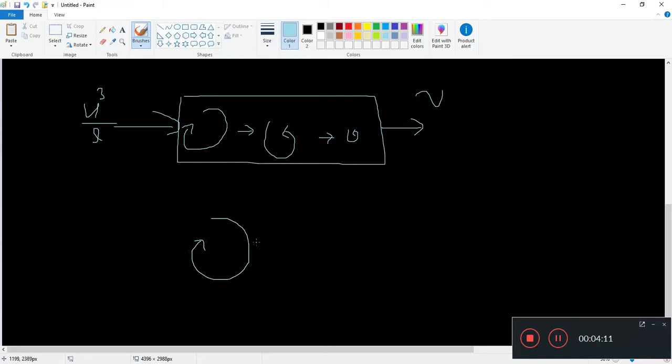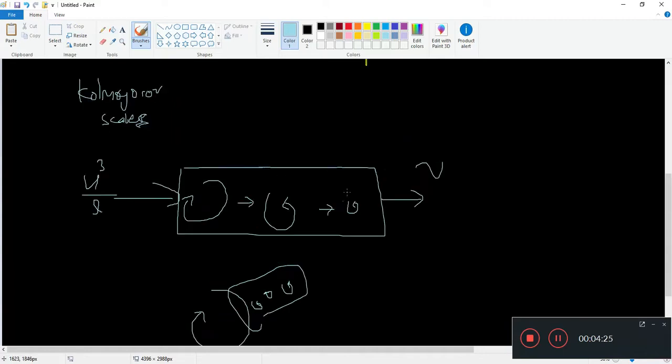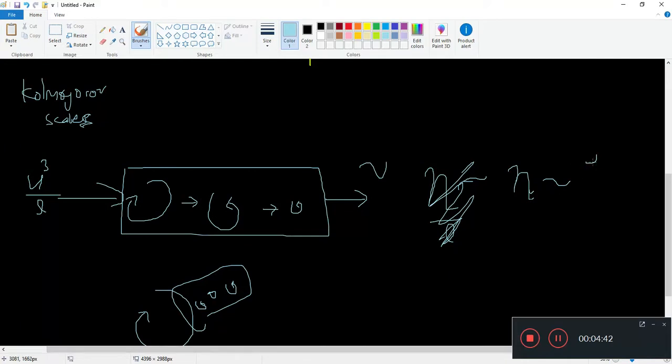If you have a big eddy, you can have small eddies carrying momentum and energy away. But if you have the smallest eddy, there is not enough energy to do this anymore. So most of the dissipation will be from diffusion, and this is what we get when we do our Kolmogorov scales. So we have nu over L. It will be eta over L, where eta goes as nu cubed over epsilon, to the 1 over 4th power. This is the Kolmogorov scale.